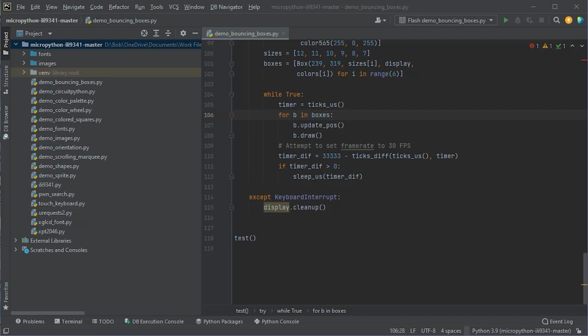So to run the code, we need to actually log on to the REPL interface for the Pico and then start the code manually. So the REPL interface is basically a console app that runs inside the Raspberry Pi Pico when it's using MicroPython. And it lets you talk directly to the MicroPython operating system so that we can see what's happening on the Pico, as well as asking it to perform various operations for us.